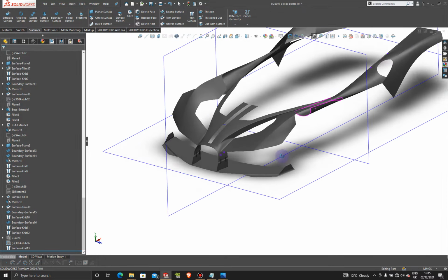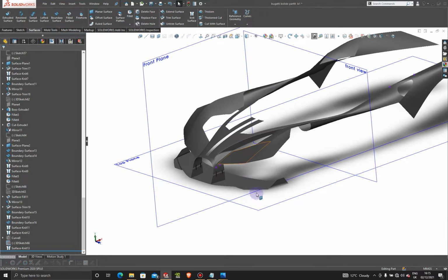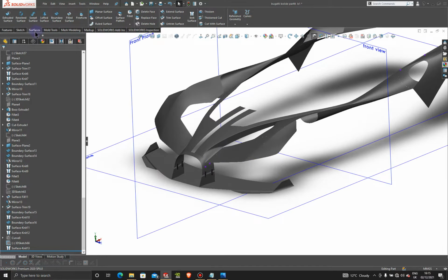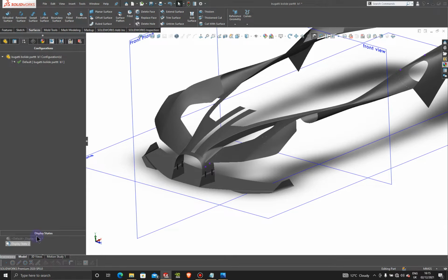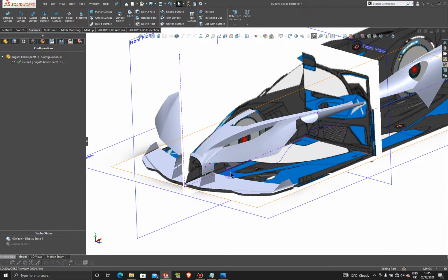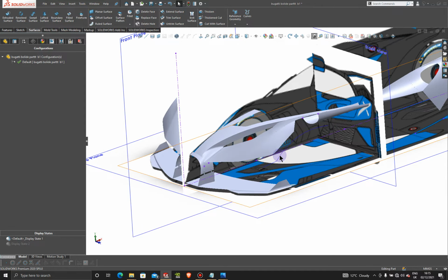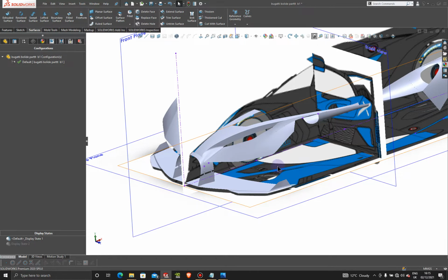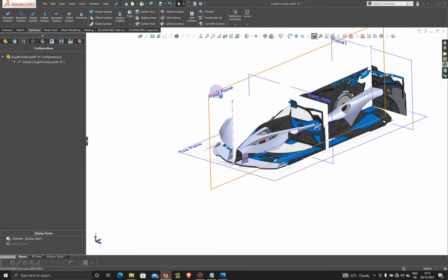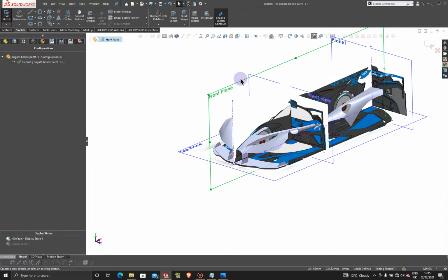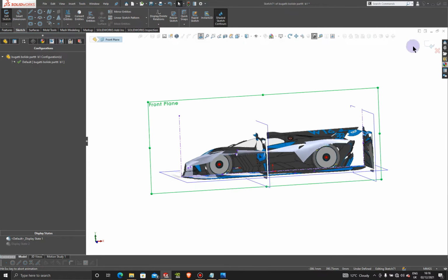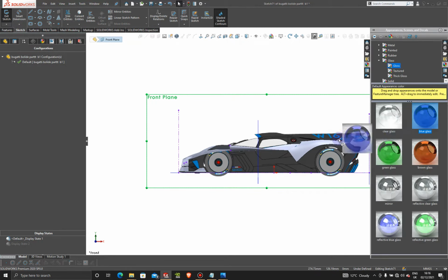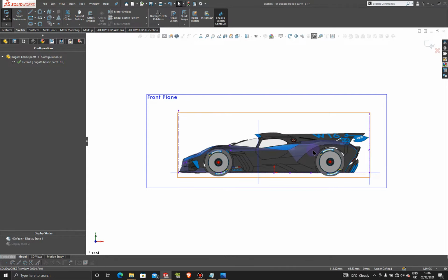So that's staying. All right, so let's attack this whole surface area here, because what we did here wasn't the right one. Let's jump into our first display state here, and then we're going to hide this 3D spline here. I'm going to hide it, not delete it. And then we're going to make a first sketch on the front plane, normal to profile.